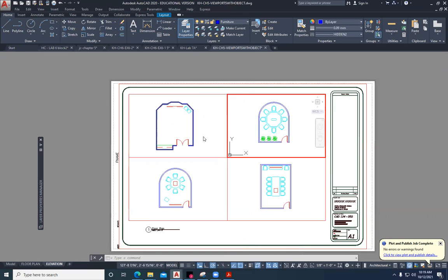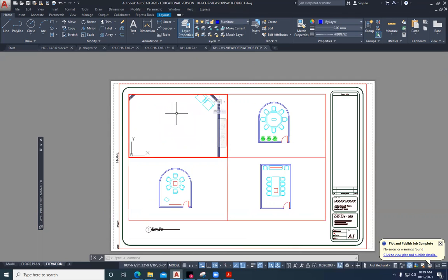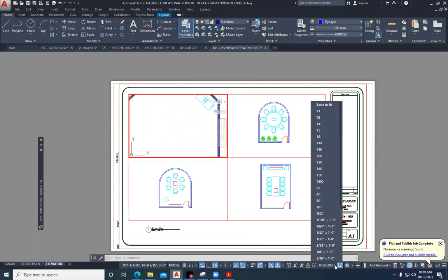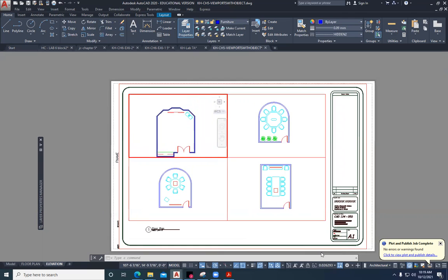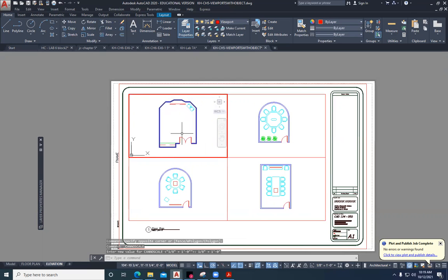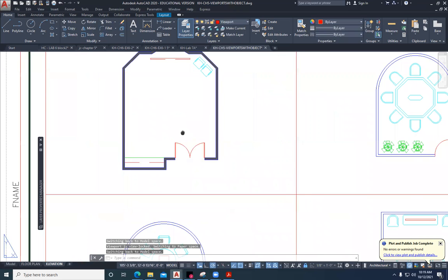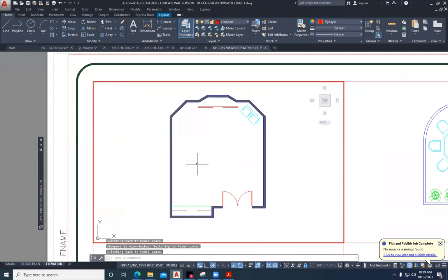And so that's a very good tool to use. We can go in here. We can then set up and I should have locked the viewport layer. Let me go back and set that up at 1/8 of an inch equals a foot. And I'll lock that. When it's locked, it's not going to change scales when you're working in floating viewports. I always think of this as like a doctor working on surgery through a cloth, that just lets him see what he has to work on.